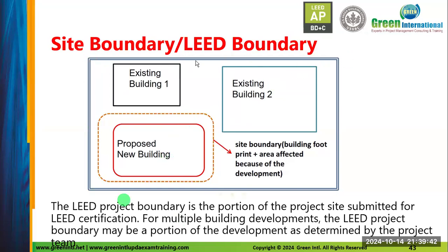boundaries. But this is not your LEED boundary. The one I'm marking now by the green mark, this is not your LEED boundary. Why? Because this is the project boundary, but it is not your proposed new building that will have LEED certification. This is the boundary of the project and its management, with a dotted line including landscape and parking area related to the management of this building.